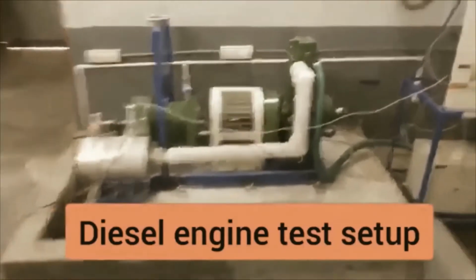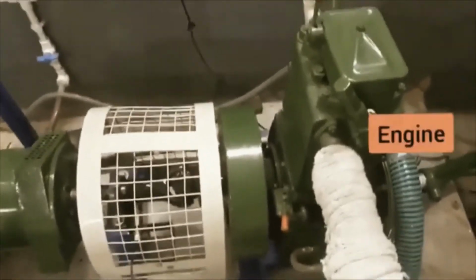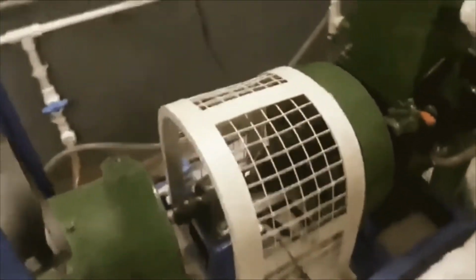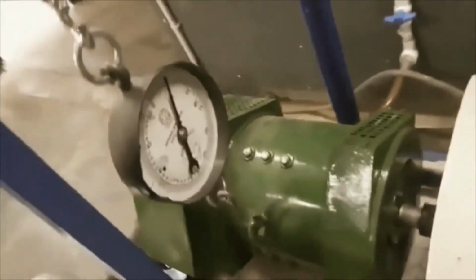This is our diesel engine setup for performing the heat balance sheet and Willans method. This is our 4-stroke water cooled diesel engine. It is connected with the electrical dynamometer, which is connected with the crankshaft. You can see the tachometer, which we use for measuring the crankshaft RPM. There is a spring balance coupled with the dynamometer for the load condition.